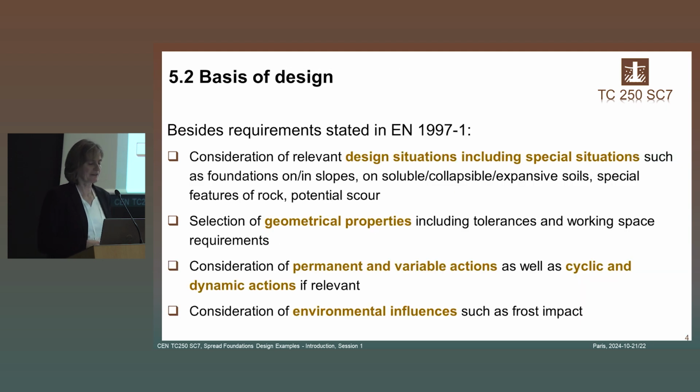Now the basis of design is provided in subclause 2, so 5.2. There's reference made to part 1, but other than that, it is stated that certain design situations for spread foundations need to be considered, including special situations such as the ones mentioned here. For example, foundations on slopes or on soluble, collapsible or expansive soils, special features of rock, because now the code also considers rock explicitly, or in this case also potential scour, which may cause failure of a spread foundation.